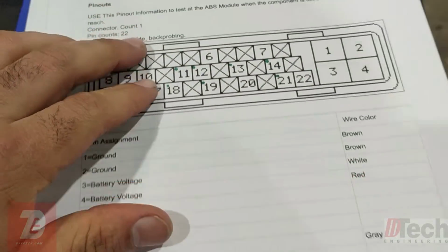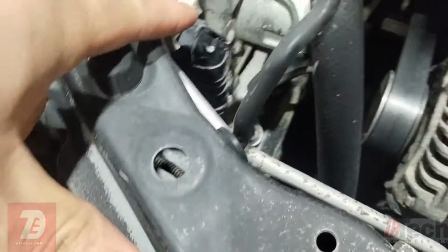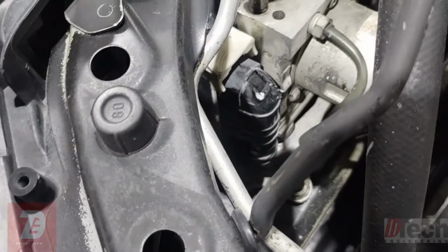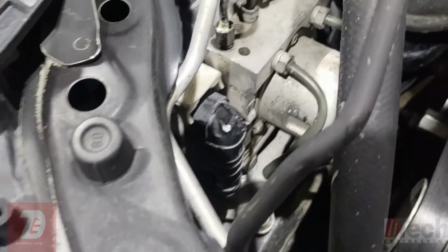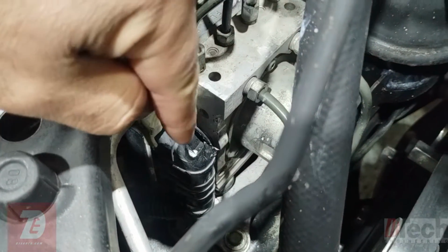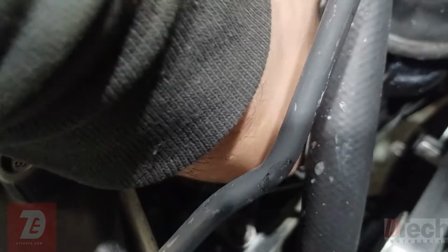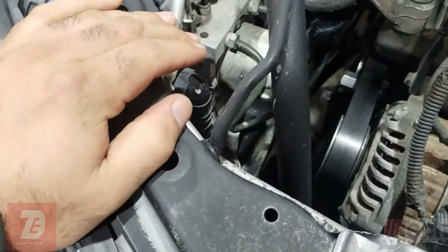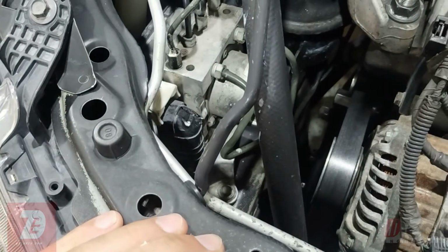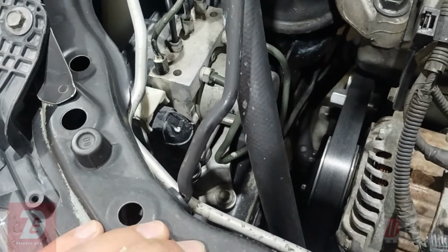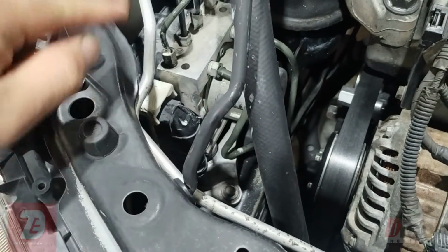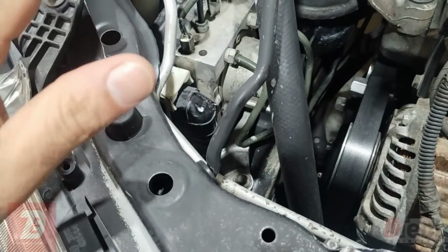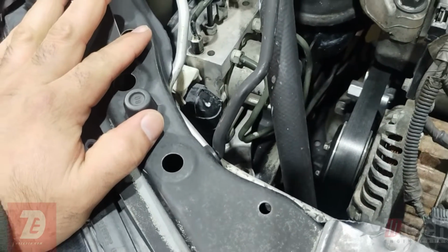So I'm going to unplug from the ABS module, which is right here on the right side, so I don't know if it's going to be a wire damage issue or who knows. I'm going to unplug this connector and ohm out the two pins per sensor for each wheel, and get known good values from start to finish, looping around, ohming it for each sensor. Then we'll look at what the right front reading is and compare all of them.